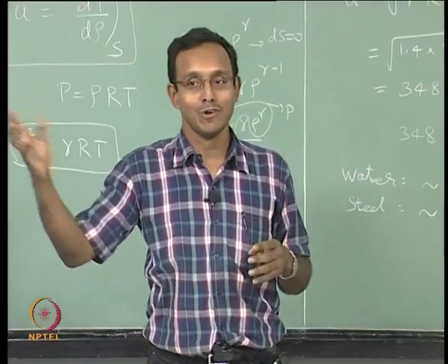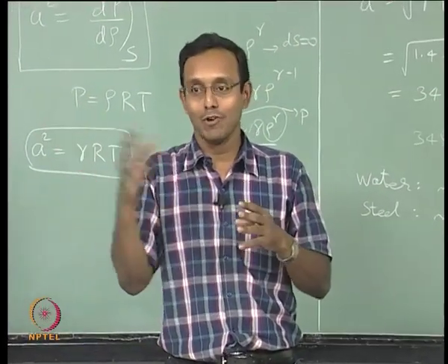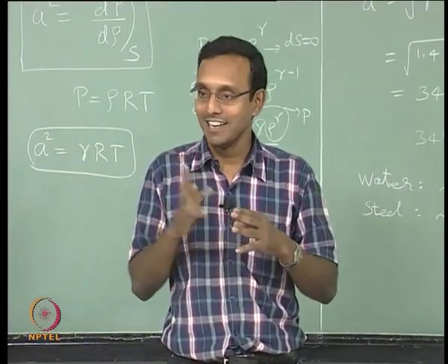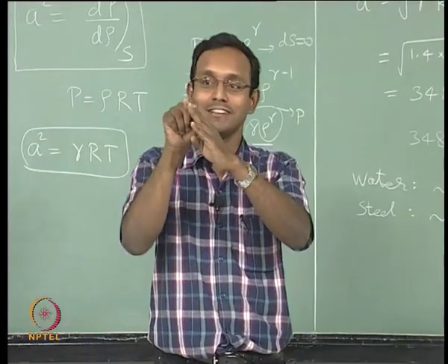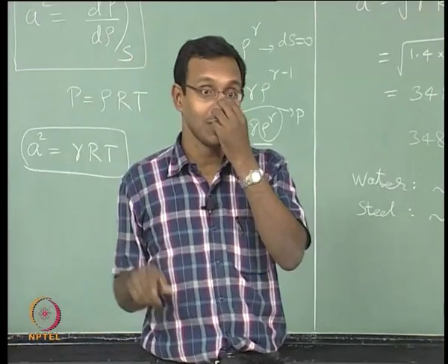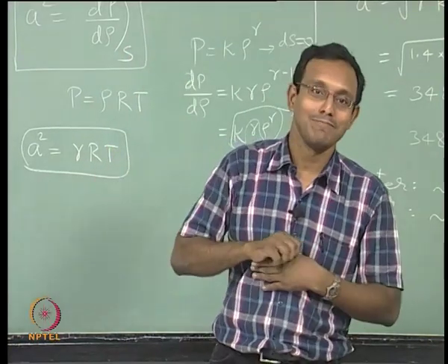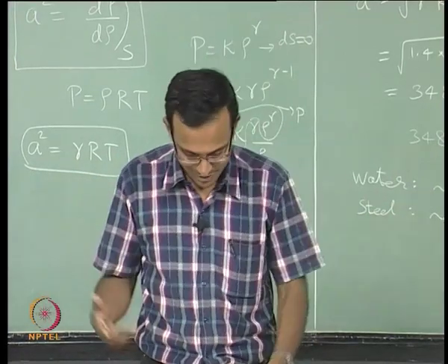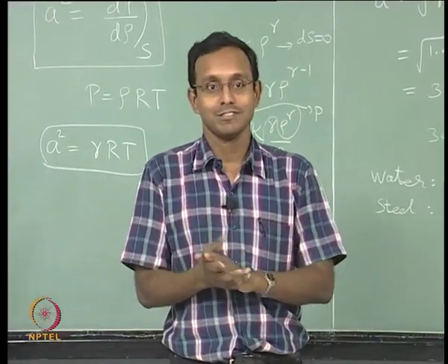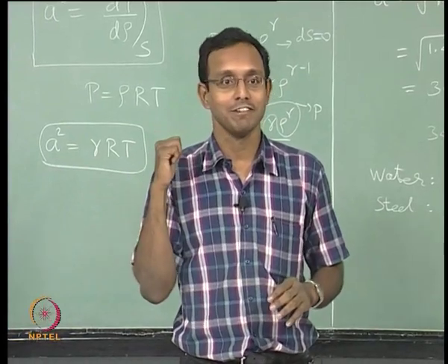After we go to a lot more flow over different bodies, I will start telling how this expansion will go and hit this compression wave and start damaging it, they will start cancelling each other, all kinds of such things will happen. So it will be helpful to think about it from a simple wave perspective. Later we will go and complicate it with strong waves. As of now we are still thinking weak waves.